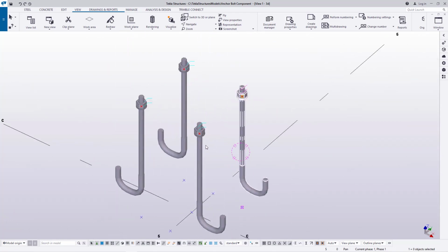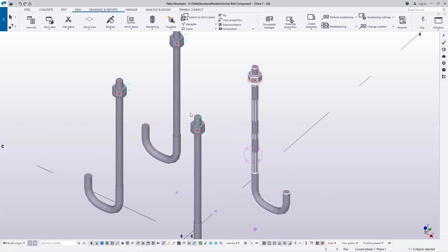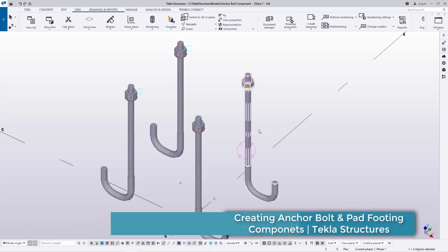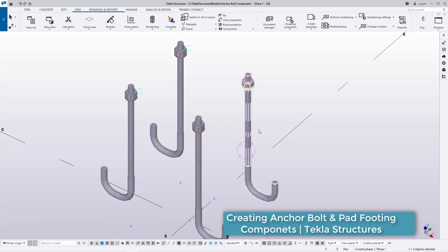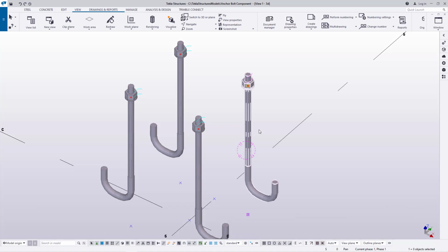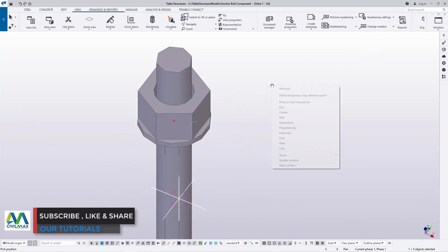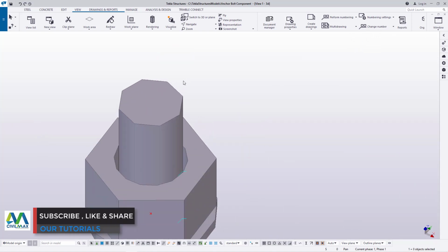Now I want to place a bar that will be binding these 4 bolts, so that when the casting is being done, these 4 bolts will not change their dimensions. In short, this binding bar will make sure that the measurements are not interfered with, however much disturbed by a vibrator when doing the casting. Now let me come here and place my binding bar.